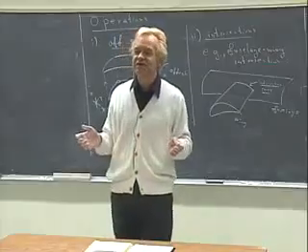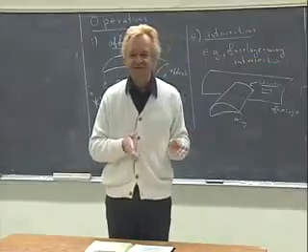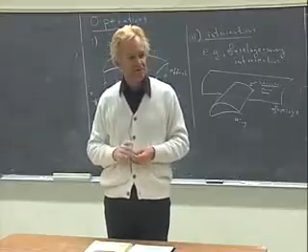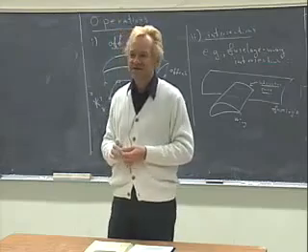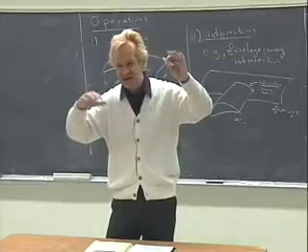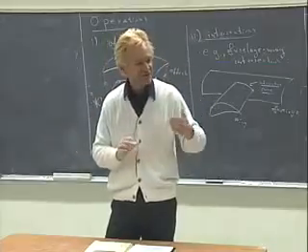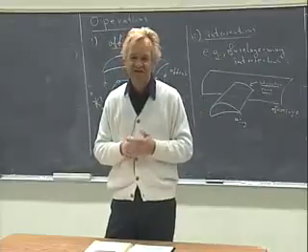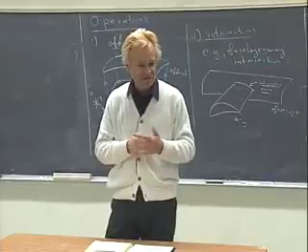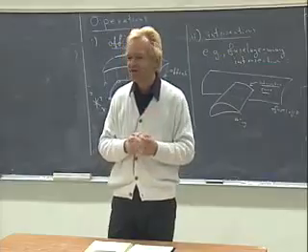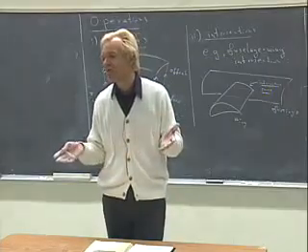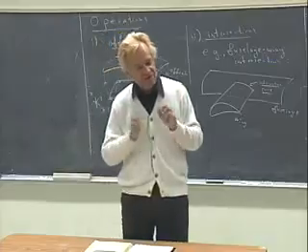Now, at some point, a conceptual study or design study of an artist or designer has to become an engineering, precise, right? Design. So then you have to take your initial conceptual design, which is kind of like wiggly and oscillating and not precise. You have to translate that into an engineering representation. For the engineering representation, you have to worry about these things like Bezier representations, B-spline representations. So everything has to be exact, right? Everything has to be down to at least 1/10 of a millimeter precision for a car body, probably even more, right? But this is what we would like to see, right?